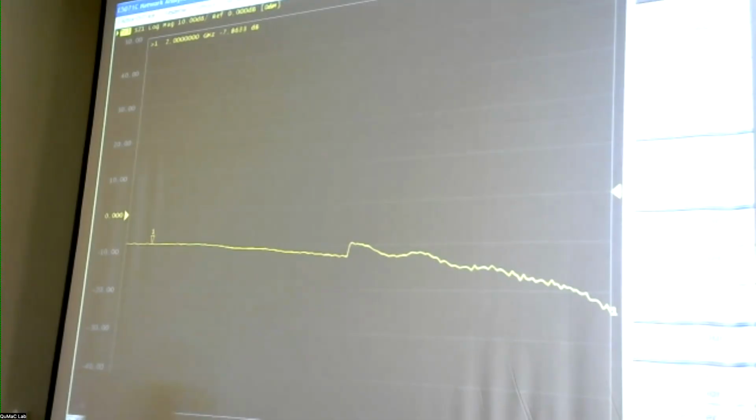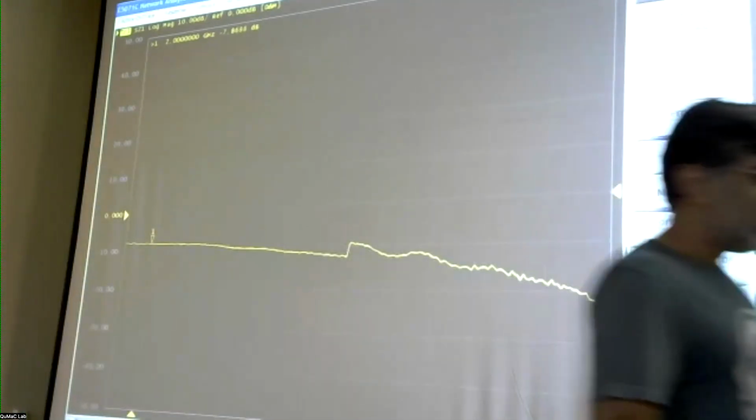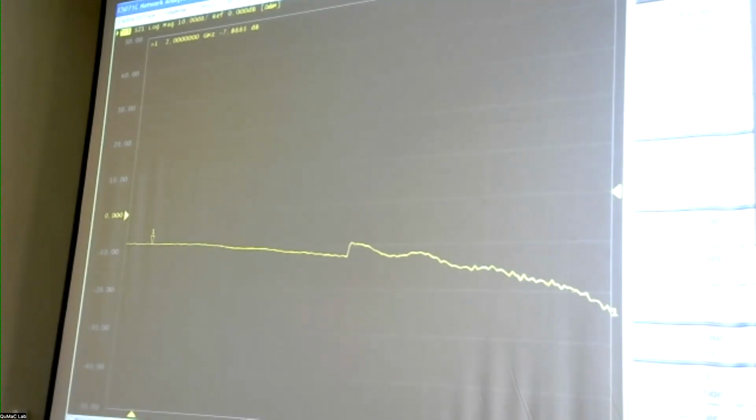So you have to do this calibration. There are more sophisticated automated calibrations as well, because here what you have to do is that you basically say connect the open, press this button, connect the short, press this button. But you can also have a fully automated one. So this one is USB powered, so you connect it to the vector network analyzer, connect two of the ports with the cables you are going to try to calibrate out, put it here and just press one button, and it doesn't work exactly the same way in the sense that it doesn't go to open, short and load things, but it uses some other known standards. And that allows it to remove the effect of any cables involved.